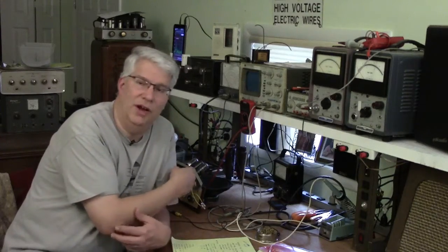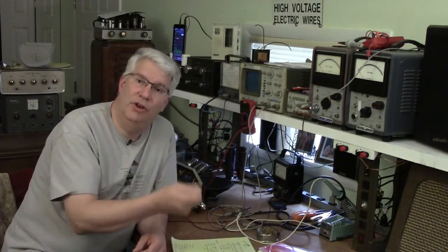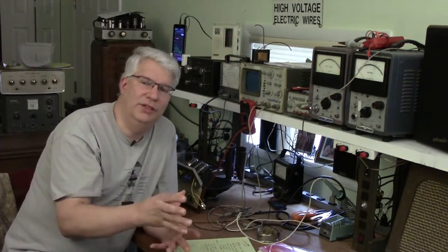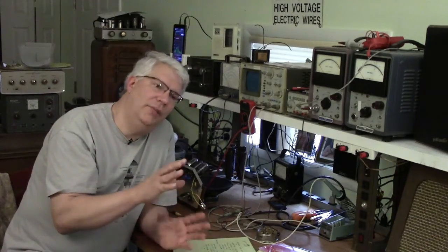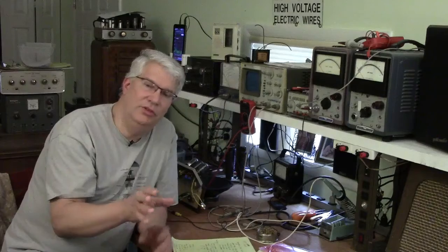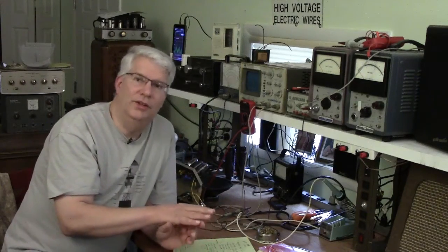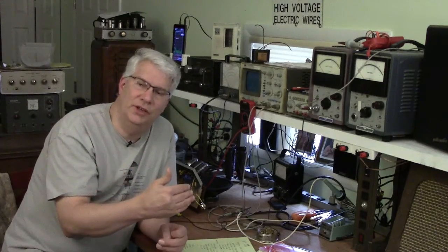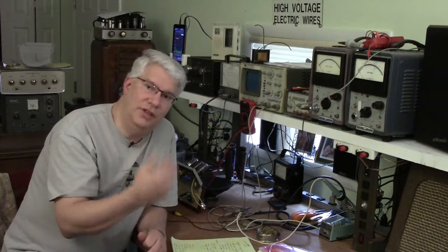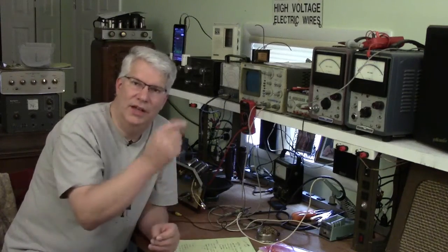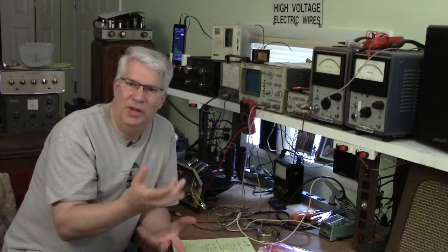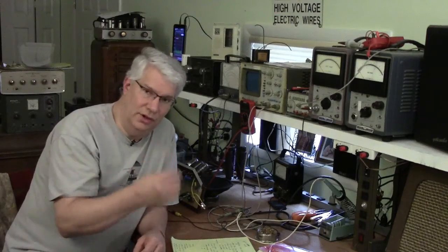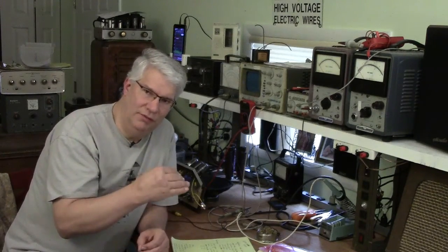So what I did was I took this amplifier and I took the 50L6 and put it in triode mode. I did some measurements, and then I have a complete example of how to do load line placing for triodes. And then I also have a complete example of pentodes. We'll go over the triode one first, all the steps involved in going from a data sheet that only has a plate characteristic. We are going to go through the data extraction, how to take that and actually create data points from a PDF document or from the data sheet. And then we're going to go through the code, and we'll set the bias point that we've chosen.